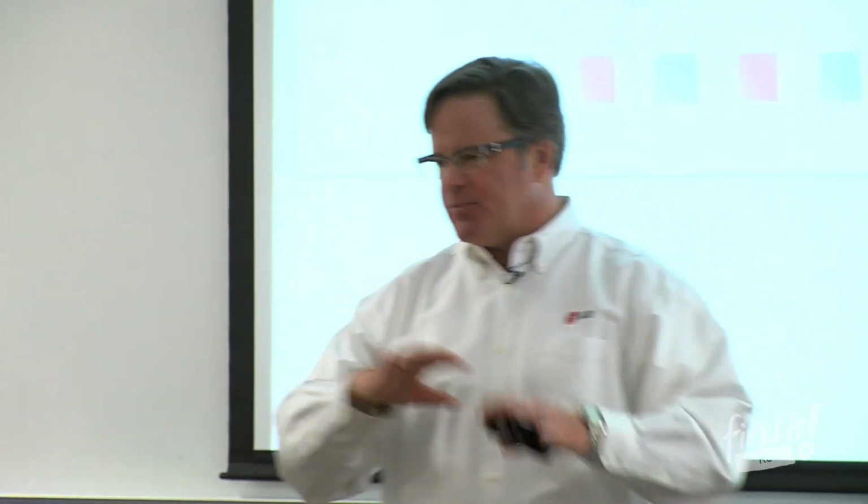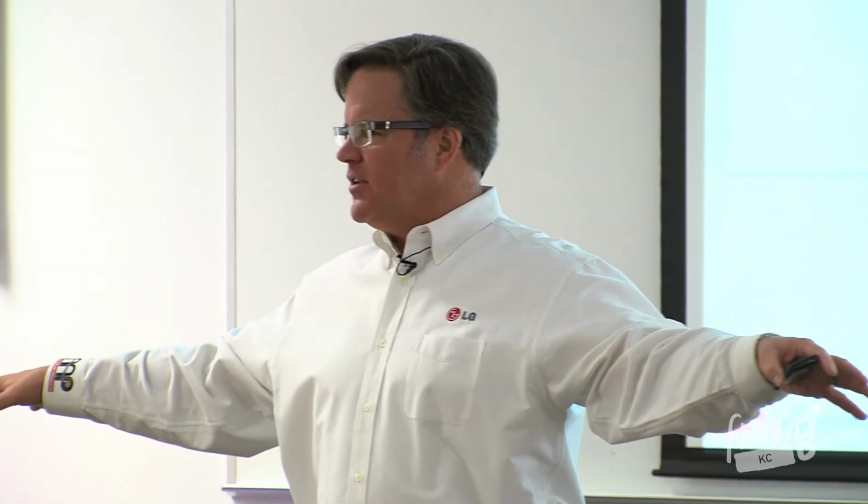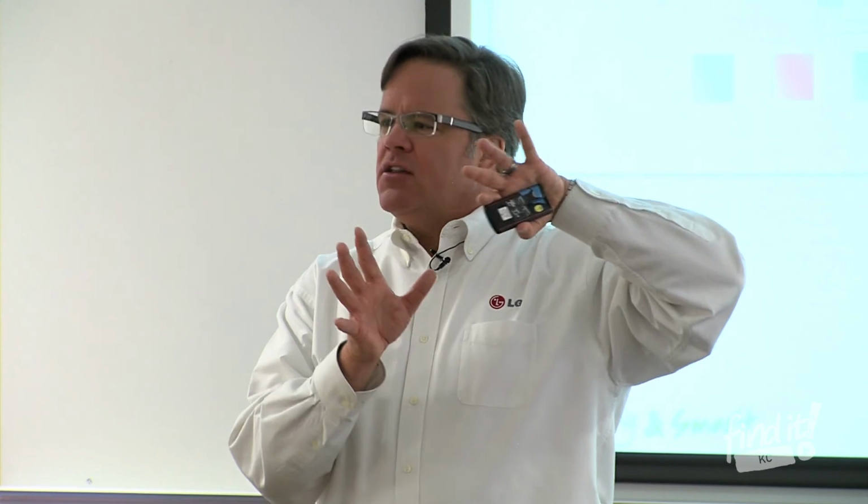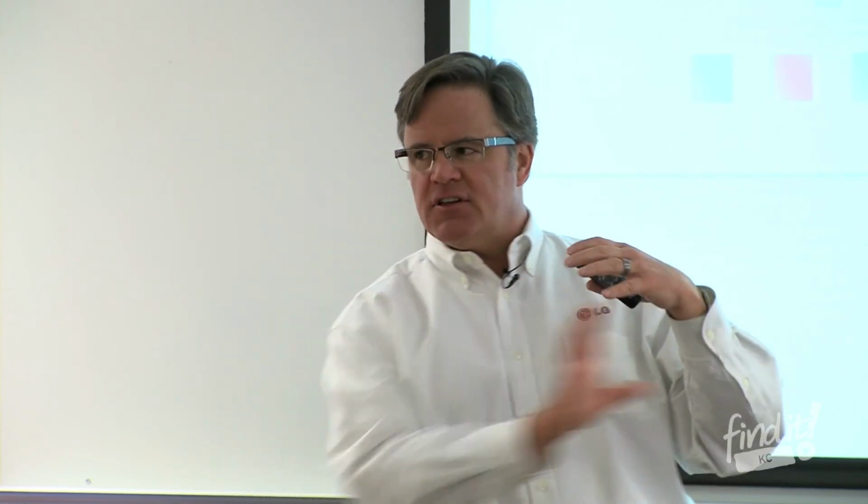Okay. The reason I ask is, let's pretend it's rooftop VAV. So you've got a few different rooftops dealing with a few different sections of this building. This gear is very fun because you're able to start adding gear and starting up units while you still have some of that rooftop VAV operating. Then, as you hack off enough legs of that rooftop unit, it's not going to operate efficiently anyway, so that's going to decide your staging, so to speak. If it's boiler chiller, you run into that same thing.